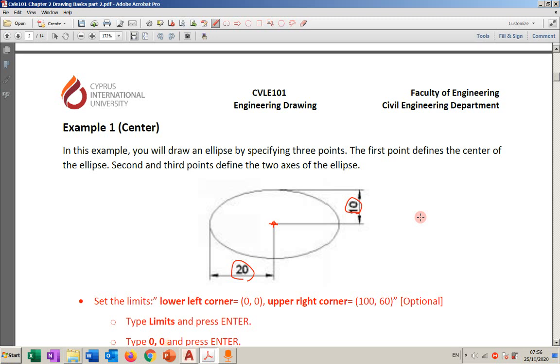So the location is supposed to be exact, so that when the machine came and they installed it over the location, it will fit the bolting place. And we have many more applications for those coordinates. So on a drawing, if you don't have a coordinate, it means that the idea is not the location, it's just the shape.